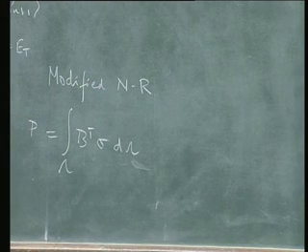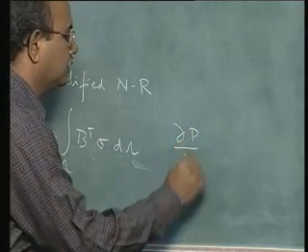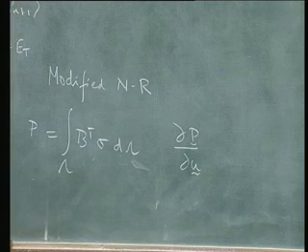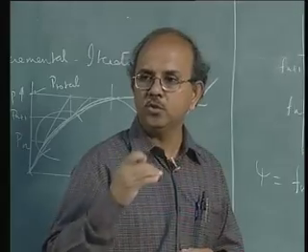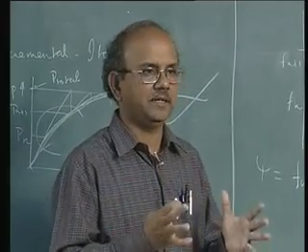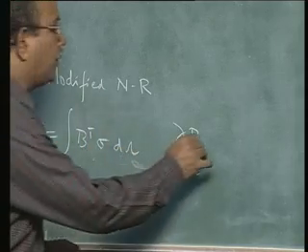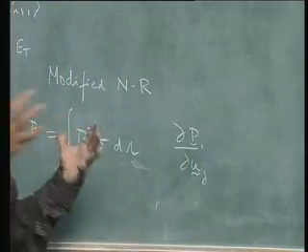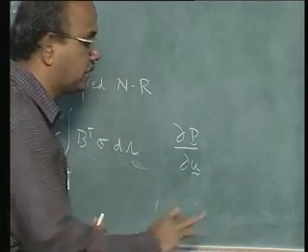Okay. So what we are interested in is what? ∂P by ∂U. Of course, these are vectors P and U. So this results in a matrix, with entries ∂Pi by ∂Uj, Kij. If I call the resulting differentiation Ktij, then ∂Pi by ∂Uj would define my Ktij and so on. We will see more details again later.